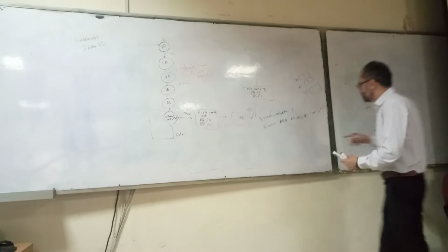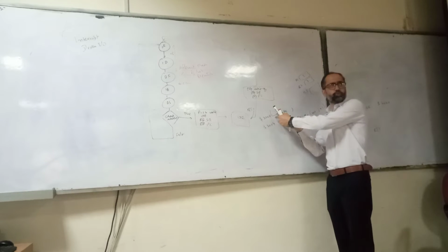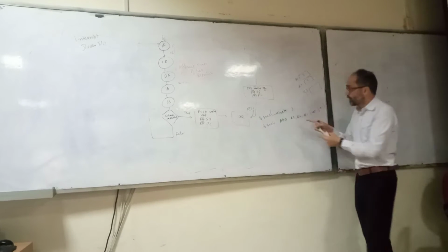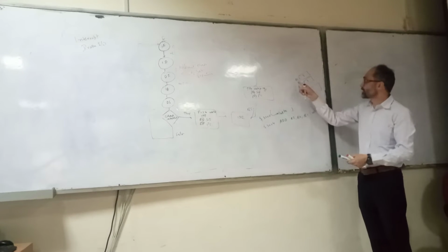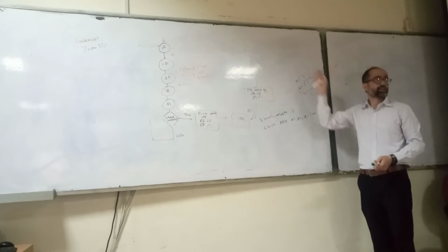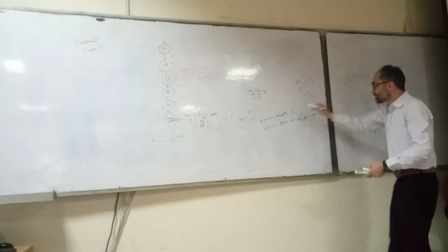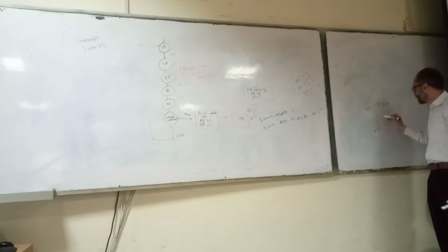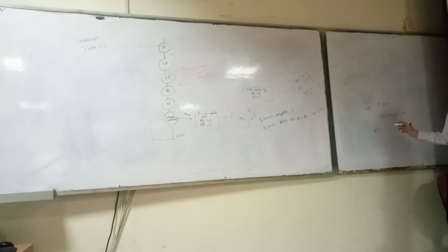Now let's assume that before this program was interrupted, what are the working registers for this instruction? The working registers are R1, R2 and R3. Let's assume these are the only 3 working registers. Once control is transferred to the interrupt subroutine, let's assume it modifies registers, like if we say add R2, R5, R6. Now R2 is modified here.